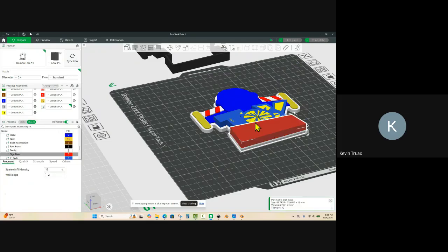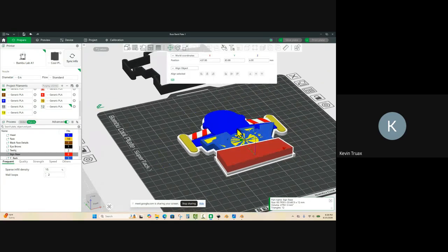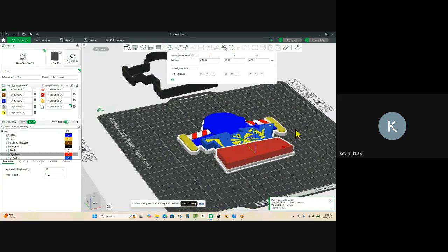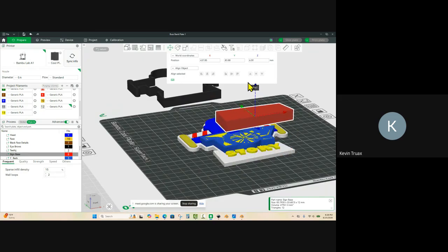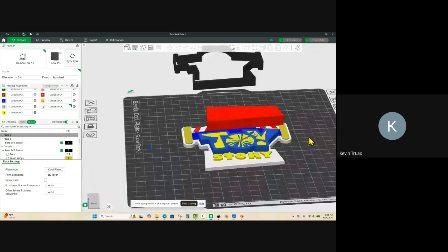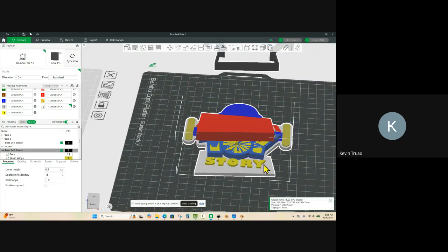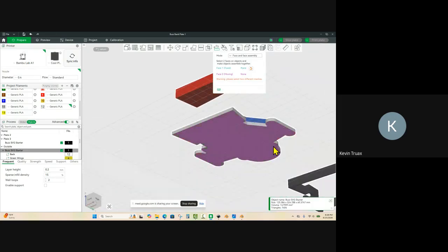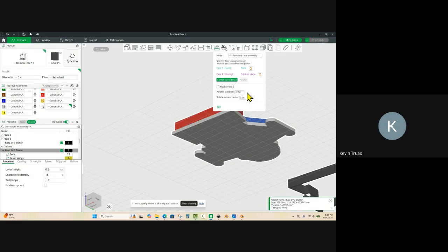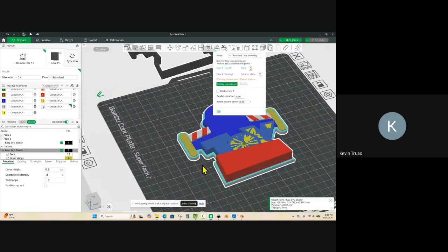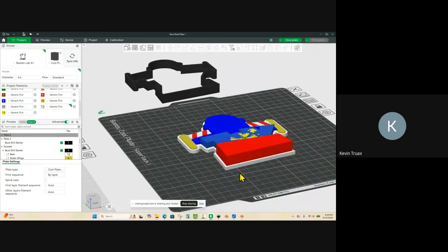So we click the red, go to move, and we're just going to move this an arbitrary amount. It doesn't matter really how much we move this, something like that. Okay, we just need it up out of our way. Select the assembly, go to the assembly tool, and set your work plane. This is your work plane right here, this face. And then we're going to drop this to the work plane by clicking the bottom of that face and hitting 0. Zero that value out. And there you go. Now our red piece is sitting directly on top of the white piece.